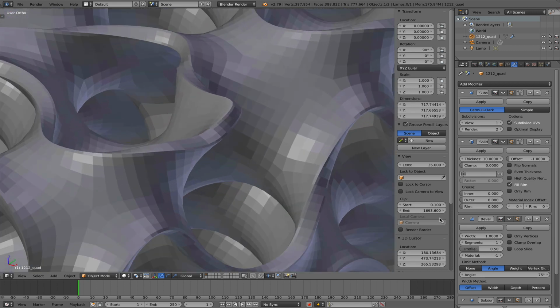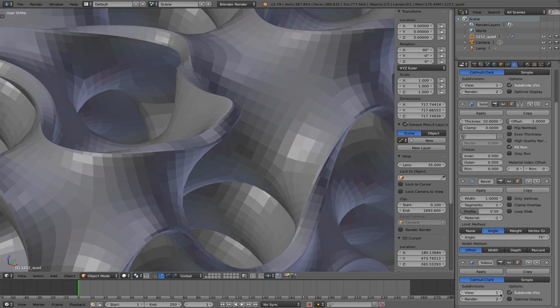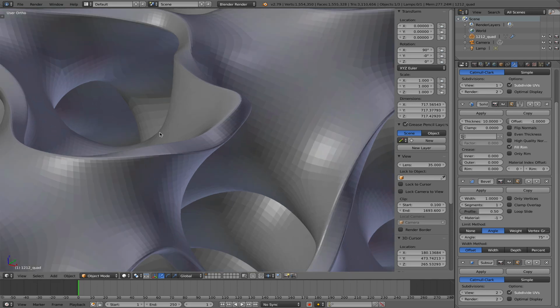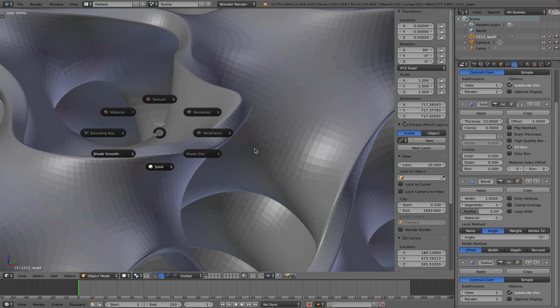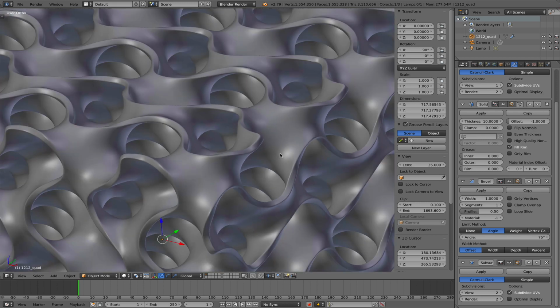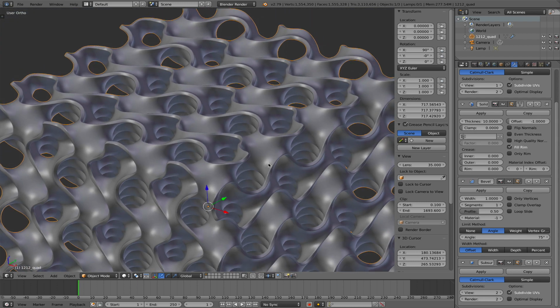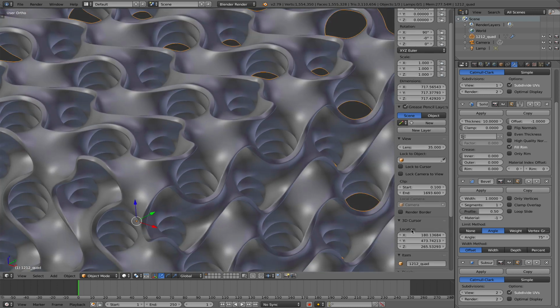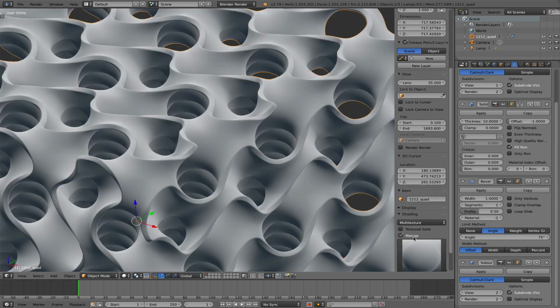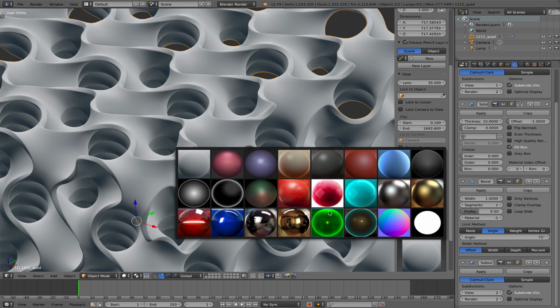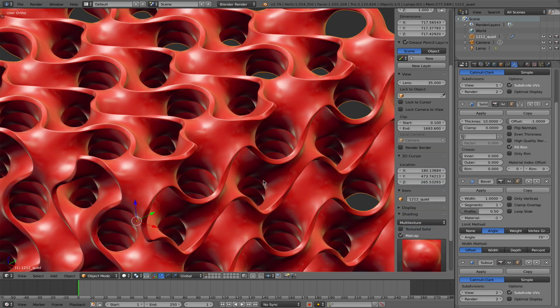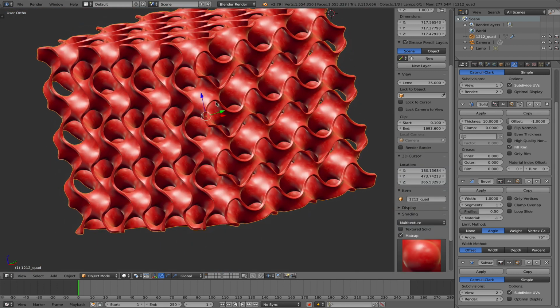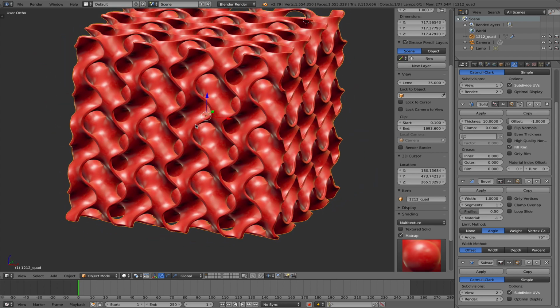So we can see this makes it very fine and yet finer. And I switch this to smooth shading. And this is basically how smooth this would look when imported into Fusion 360. So maybe we want to give that a little bit more of a shiny surface. I'm going to turn on Matcap and pick something a little bit more shiny. And this would be the final object.